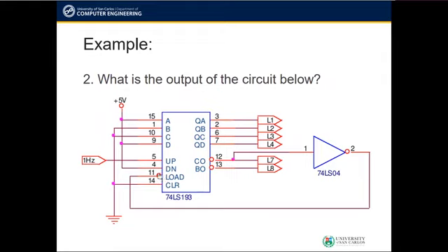That will trigger the load operation and cause the counter to continuously load the 1001 input at the parallel load inputs. The other input pins here will have no significant effect to the counter behavior in this implementation.